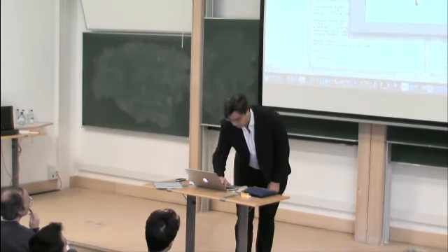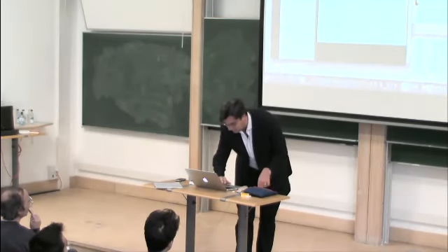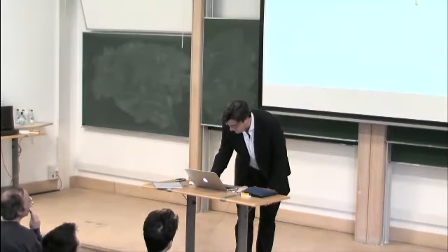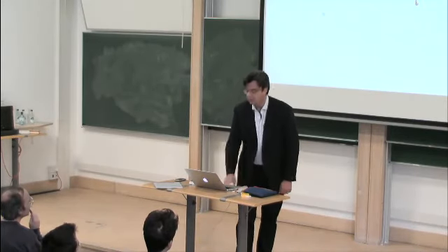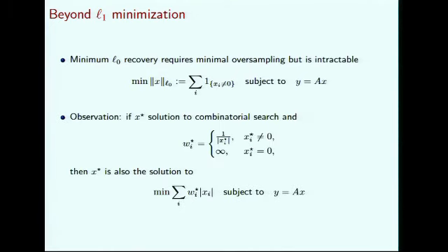Okay, so what is this algorithm doing? What is it that I just did? It's very simple. I don't want to spend much time on it. Right? So if you truly have a sparse signal, but somehow the sparsity is a bit too high for L1 to work, then there's a reweighted L1 heuristic that works very well in practice. And what this heuristic does, it does something like this. What we would really want to do is minimize the L0 problem, which is just counting the number of coefficients that are not zero, but we can't do it.